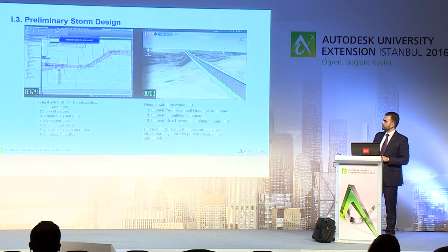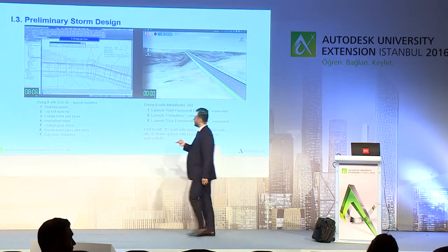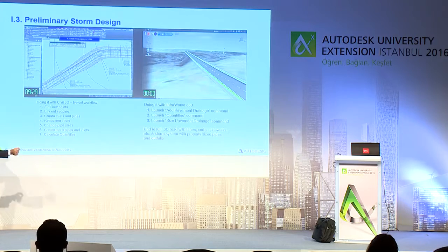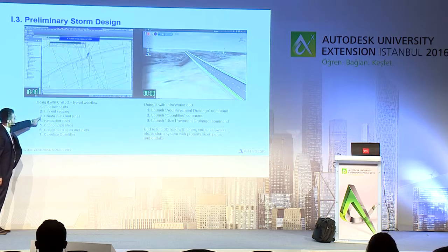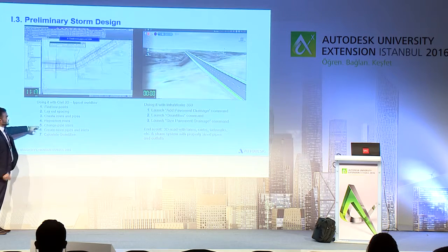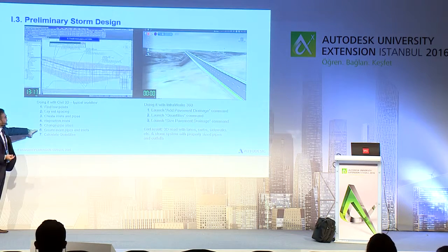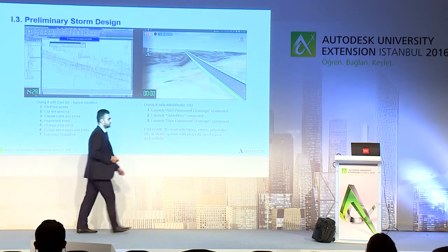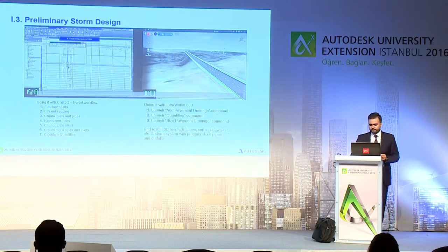The designer is going into finding the low points first. So he has to analyze where the low points are in our design. We have a dip. We have to analyze those, lay out the spacing where I want to place these structures, create the inlets and pipes, reposition them, change the pipe sizes to accommodate the flow of the storm that's coming onto the road, create more pipes on inlets if required, and finally calculate the quantities. This process takes, I guess, more than 20 minutes, and this is with an expert in Civil 3D.